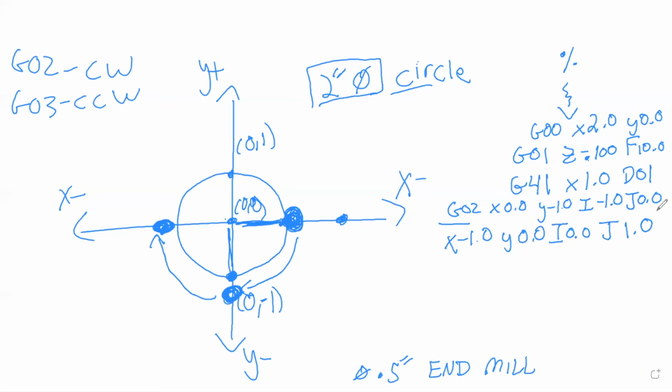Right? So you got to remember, every time that we move incrementally, we are restarting at 0. Okay, so our incremental movement, this is our 0,0 here. So if we move up to our swing location, we're moving up in the positive Y. When we were at our first location over here, we reset 0 for incremental movement. Our swing point was over here. So that is a negative X value. That's why in our first line, it was negative. In our second line, it was positive.